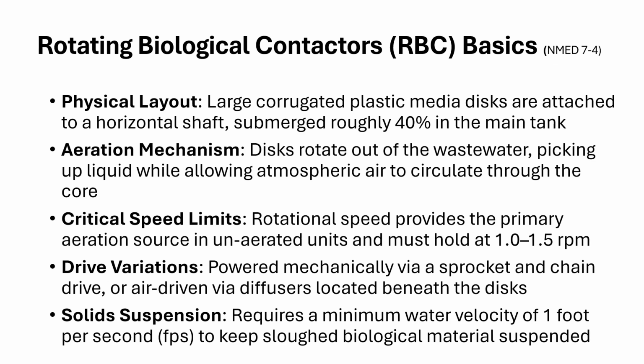Remember, the magic number to keep solids in solution is 2 feet per second. That's in our collection system, and we want this to be less than that 2 feet per second, because if it's greater than 2 feet per second, we're going to strip that slime layer off of those corrugated plastic surfaces. So we're going to allow the suspension of biological material at 1 foot per second here.